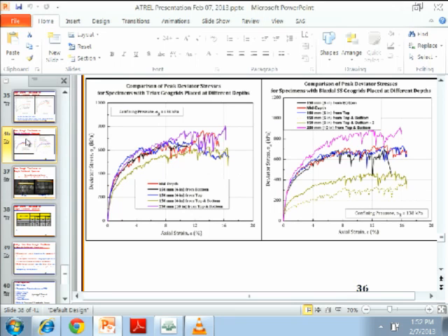Okay, you should have some stronger beliefs in what you're doing and explanations of what this test is all about and how it relates. But we are testing with clean ballast. You should always realize that running the test in the lab with only up to maybe 1,000 or 10,000 cycles is only the beginning and a little bit of what's happening out in the field. In the long run, when you have 90 MGT, million gross ton, we were able to relate that to 600, 700, 800,000 load cycles as opposed to our at most 1,000 or 10,000 load cycles.